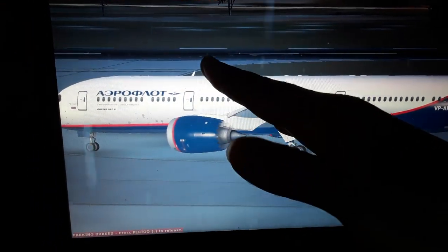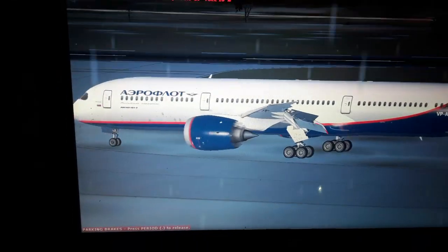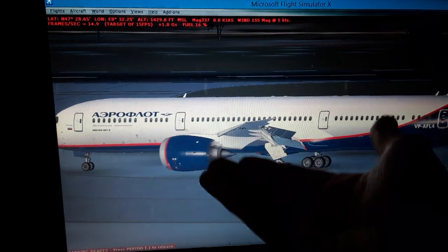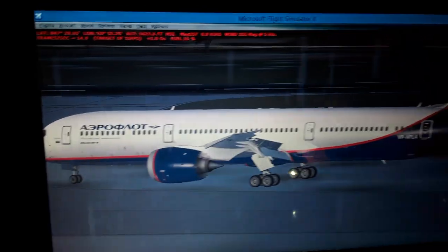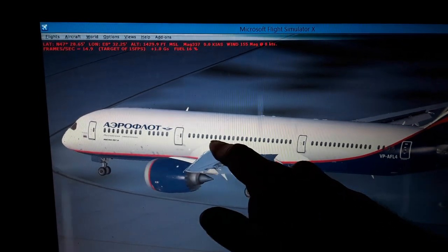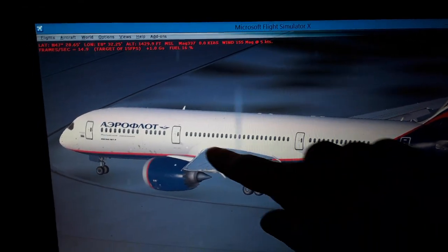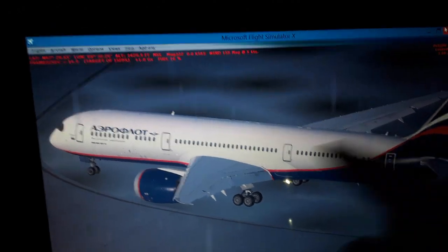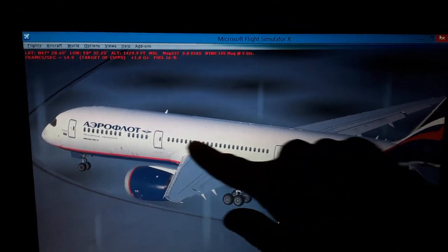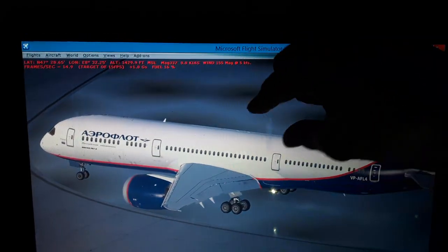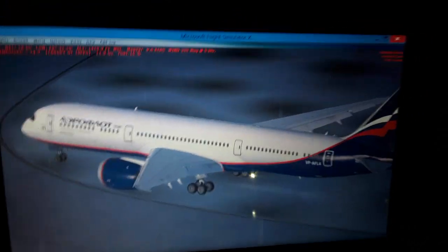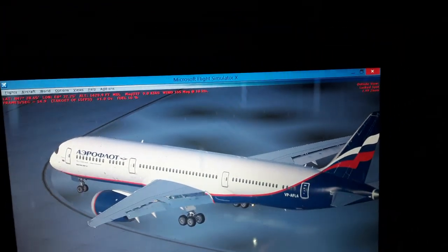Also, as we fly, we have a positive angle of attack, so the airflow is moving much lower below the wings. We have higher pressure, which pushes the wings and the weight of the aircraft up into the air as we fly, using Bernoulli's theory of fluids. And then you can see the top surface of the wings is more curved, so the airflow is moving much faster above the wings, which sucks the aircraft wings up into the air. We have lower pressure above the wings.